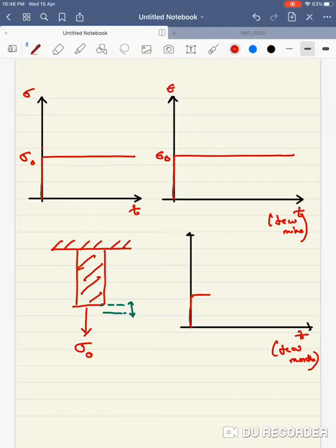So now what you see is that this was the initial plot you had, and let's say there is a robot which is measuring your strain value. What you'll see is that this has now increased. And for a long time, maybe for a week or two, this did remain constant. But then after that, even under a constant stress, the strain kept on increasing. So this is your strain on the y-axis, and it has now started to increase. And if you've left this for a very long time, maybe a few years, you come back and you will see that this is ruptured.